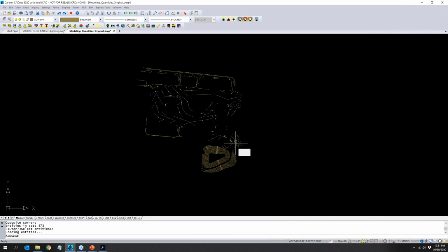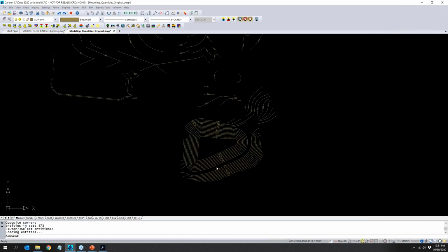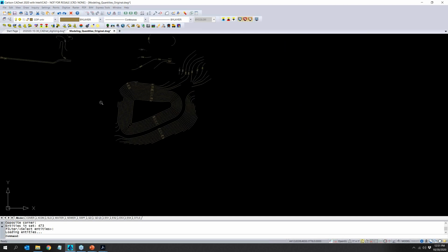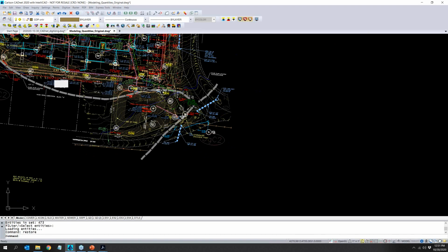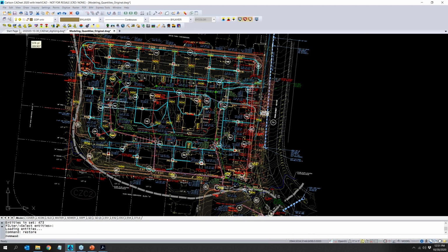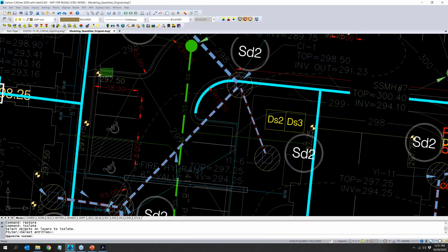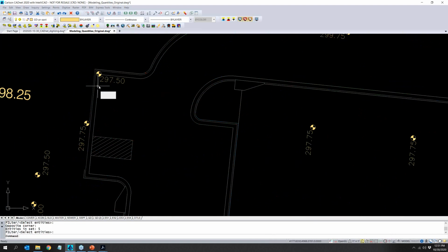Most of the time, what's going to be easier here is to put everything at 0, make sure everything is flat, 0 elevation, and then re-elevate everything. We've got tools to do contours that are in a series, to do contours that have elevation labels. Some other problems that we'll likely have to address are things like our curb lines.